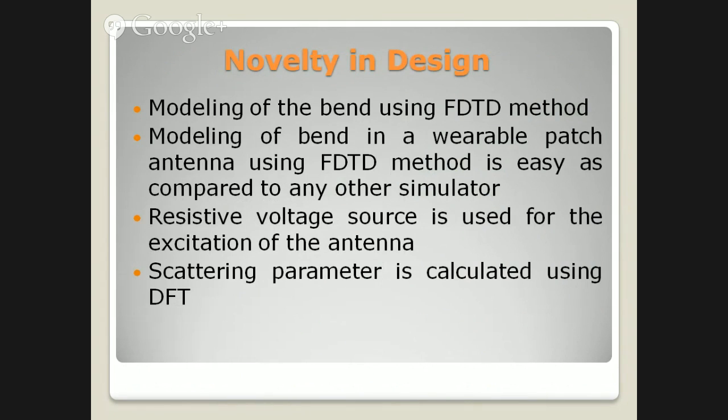The novelty in this design is that we are modeling the bend using the FDTD method, by writing a code in MATLAB. We are not using any simulator for this. And we have used a resistive voltage source to excite the antenna. The scattering parameter is calculated using DFT.